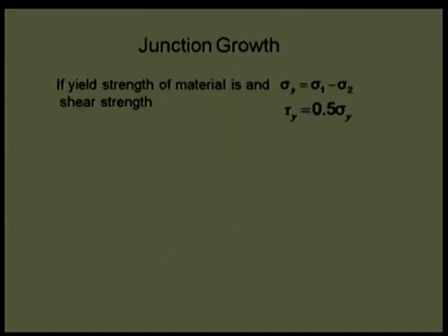So, we can substitute those values. Sigma y is equal to sigma 1 minus sigma 2, and if I use a shear strength approximation, we say that shear strength is generally 50% of yield strength, depending on which theory I am using, maximum shear stress or Tresca theory.